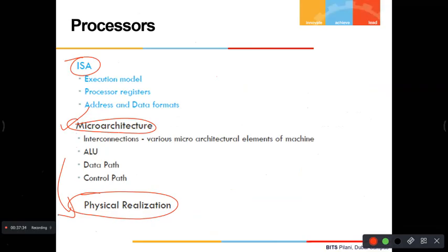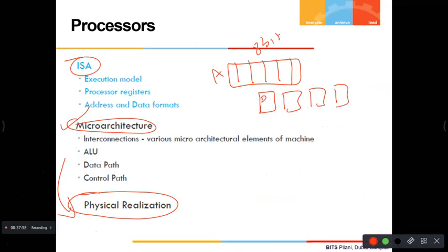I'll just simply write, see, suppose I say this is an 8-bit register, I say A. This is a register, right? I say 8-bit register. This is enough if you are only programming the microprocessor. Suppose you are a hardware design engineer, then you should write the entire diagram. What is that? D, Q, D, Q, D, Q, like that. This is also a register, but you have shown its microarchitecture.